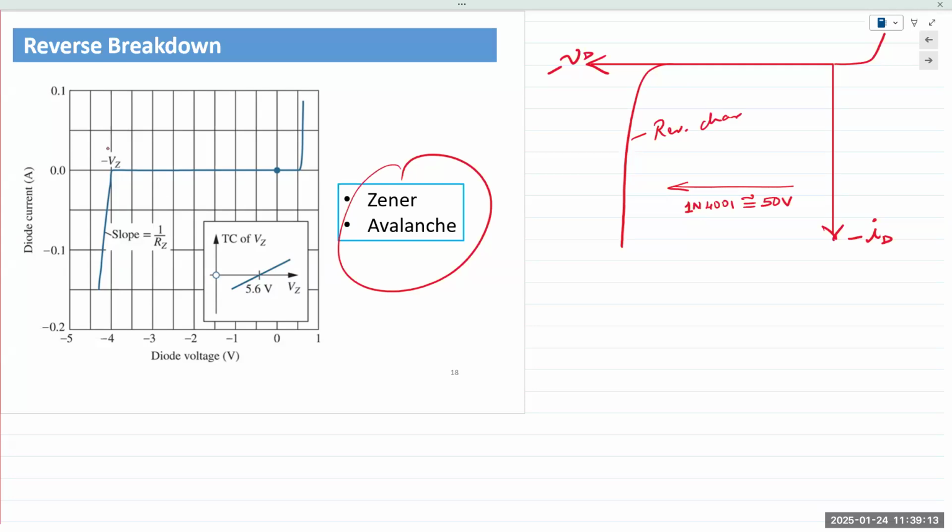So lots of charge carriers immediately start crossing over at equilibrium. Because of the number of charge carriers, the depletion region, the space charge region, is very narrow. And because it is very narrow, when you apply a reverse bias, it does not take a lot of energy for the charge carriers to cross over the junction. And so heavy current flows in the reverse bias.